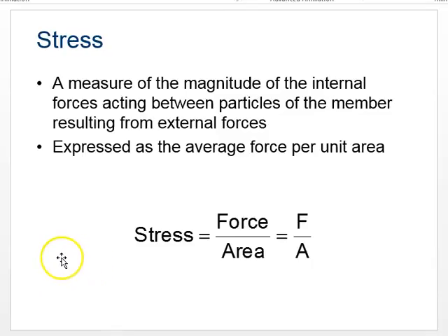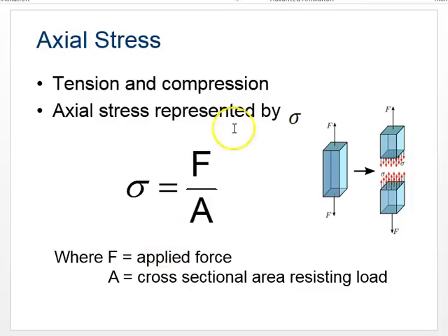Stress is an important concept. The stress is actually the force divided by the cross-sectional area. If we just looked at how much force went on things, then it wouldn't be proportional based on different sizes of areas. When we divide the force divided by the area, we get stress. And stress is represented by a lowercase sigma. This little symbol right here is always stress, and it's always force divided by area.